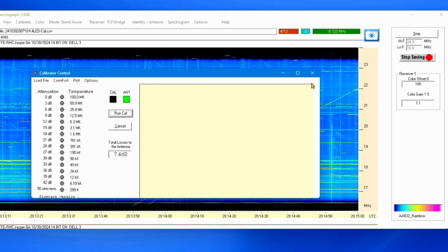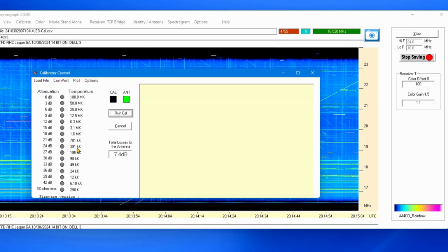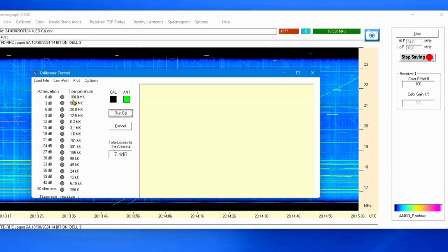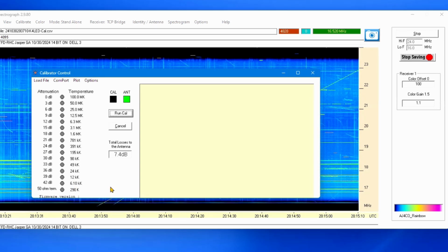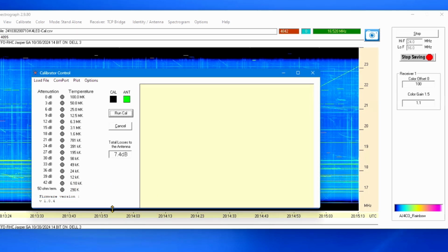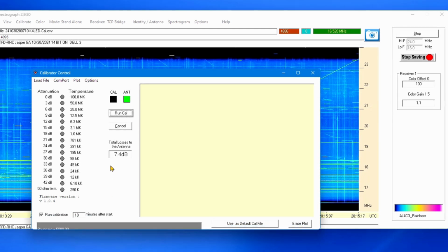This provides precise scientific citizen science level calibrated settings to compare Radio JOVE station spectrographs with other observers. Your resulting RSP1B dynamic range plot may not be perfect, but try to get the ends as close as possible to the corners.